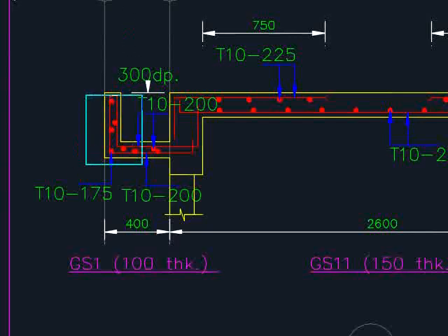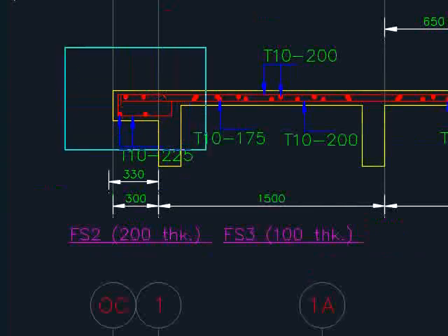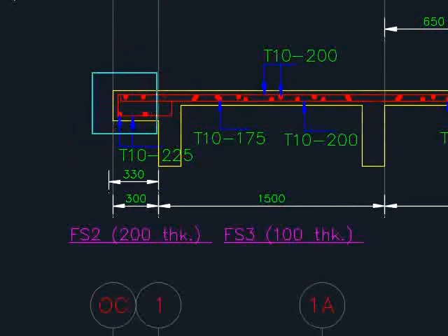This design is actually simplified, as it is foreseen that this is just a gutter with the drainage attached, which is not quite concerned about the weight. And sometimes you have something like this, where you have an extended fin here out of the beam. Make sure you provide reinforcement in order to ensure the corners are properly done.